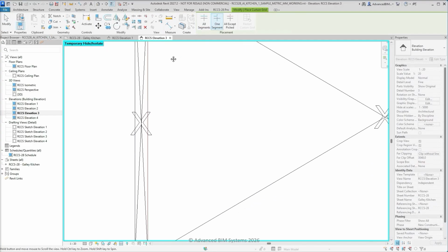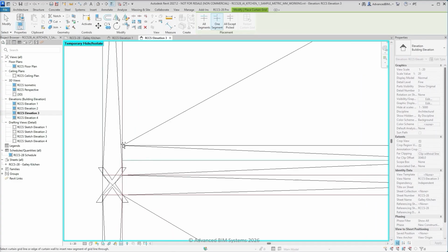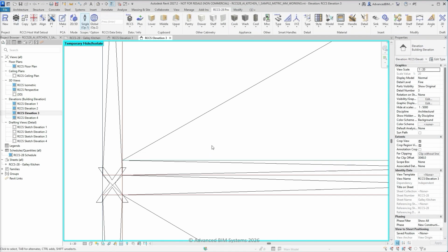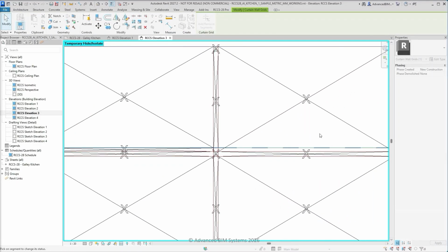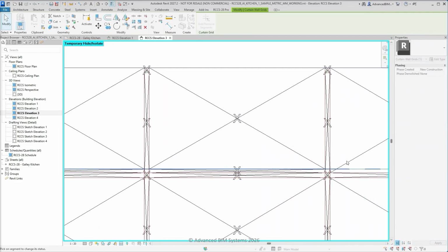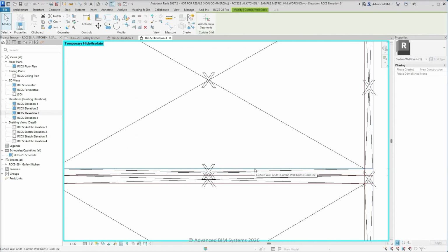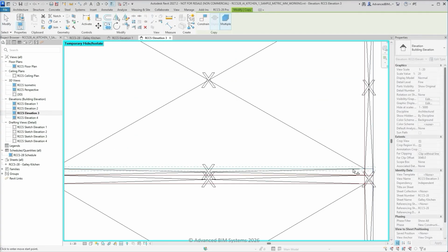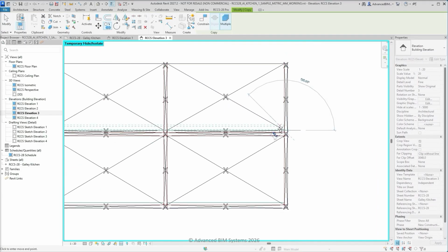The rack frame shelf grids are always placed above where the horizontal metal frame will be generated. The RCCS rack frame make function will automatically detect these grid lines and set the generated 3D shelf components in between the 3D metal frame. Once again, use the Revit copy function to copy complex grid segments rather than repeating a complex grid segment process.